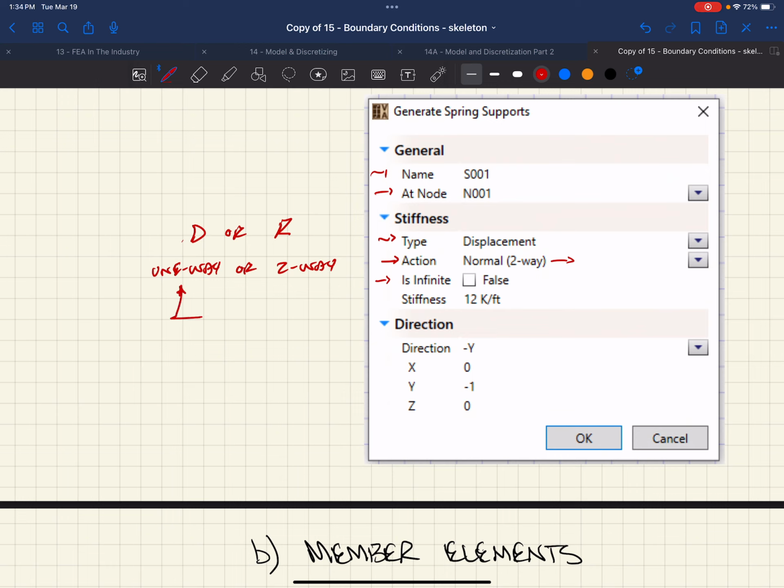One way would be, right, a slab on grade. Two-way would be, say, like a helical pier. I don't know if some of you have used helical piers before. They're basically a big screw that is driven into the ground with a hydraulic device. And then at a certain torque, it twists off the bolts on the machine used to screw the implement into the ground.